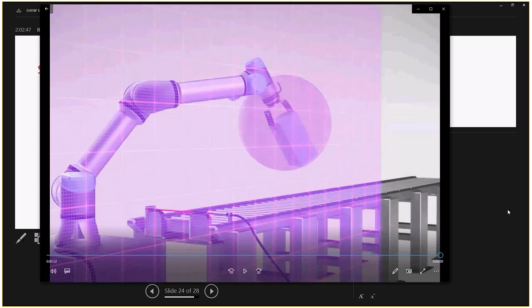That's first. Second is that if something still gets picked up, the 10 boxes, the machine will not operate at the same speed either. You will notice that something's wrong with it, because now it's working with a weight that you didn't set it to be at. So it will tell you that something is wrong. That is another step that you can put: as soon as you have, if you're normally supposed to be having 10 kilograms and you have 10.5, an alarm should go up. Those are the alarm topics.